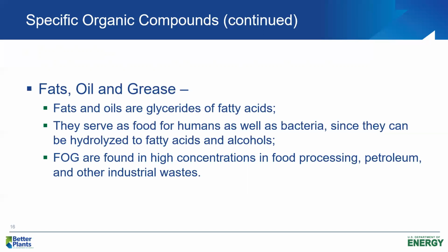So what was a 36-inch sewer now effectively became a 24-inch diameter sewer. At normal dry weather conditions, it wasn't a problem. But when we got a storm event and that excess water, what we call inflow, got into the sewer system and flows went up dramatically, the sewer line filled with water, the manhole surcharged, and the water went spewing out the top of the manhole, creating an SSO, sanitary sewer overflow.